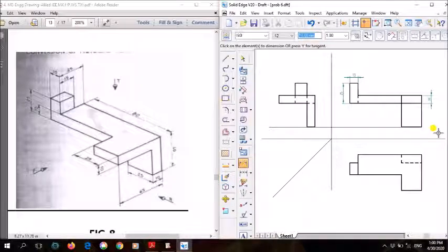Next, what can we show again? Yes, this whole height. From here again, show the height. From here to here, this distance should be how much? 1 centimeter, that is 10 mm. And the distance of the second dimension line with respect to the first dimension line should be 8 mm. Just remember this concept. So we have shown this dimension.